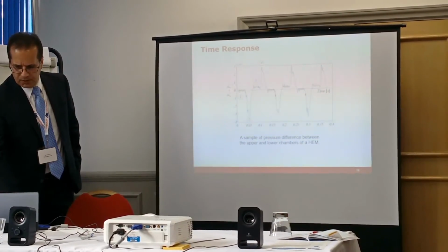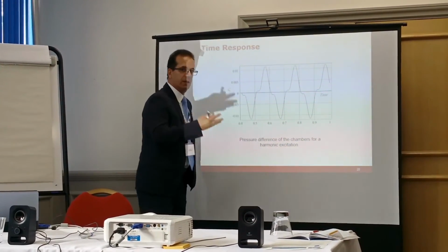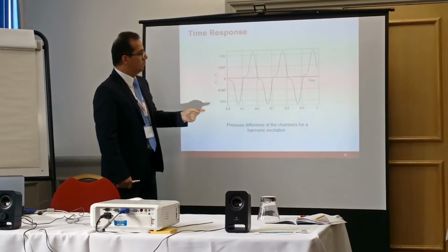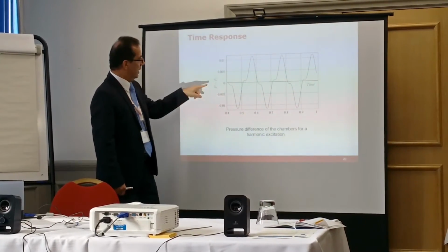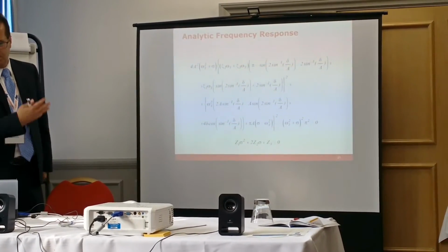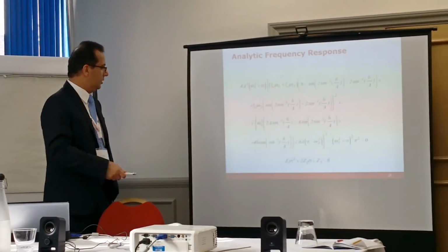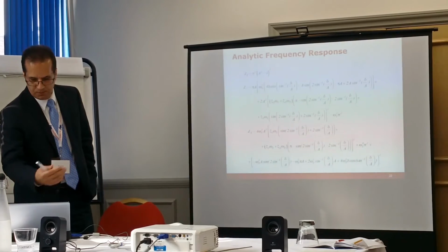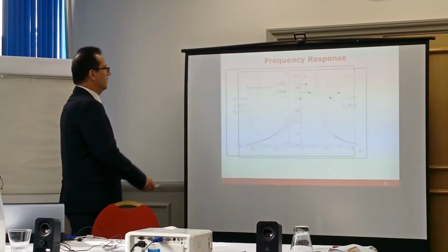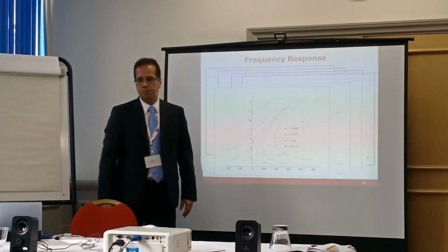Around 2006, I introduced a mathematical equation for the vibration system to simulate the same action. This is the response based on the mathematical analysis, and it simulates the same behavior fantastically. So we use that. Of course, there is some mathematics, which I skipped. This is the frequency response of the system based on the perturbation analysis that we have done. The rest of them are here. Using perturbation analysis and the equations, of course, we can find the frequency response, do sensitivity analysis, find the jumping phenomena, and so on.